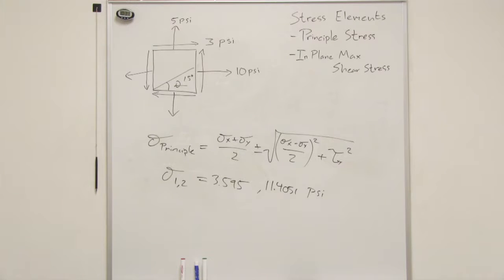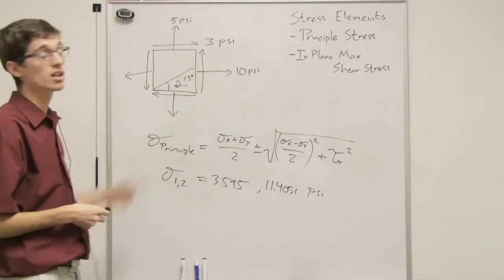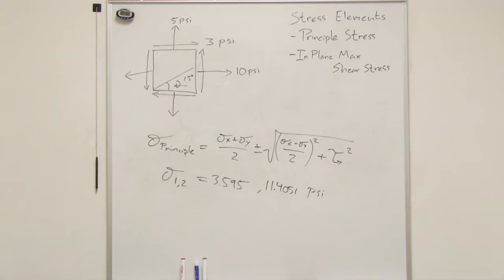And so the cool thing about principal stresses is that they occur at the point where there is no shear stress. So this stress element, if we were to draw it, would just have these normal stresses, but the shear would go to 0. But we want to find out as well how much we have to rotate it, where that's oriented.